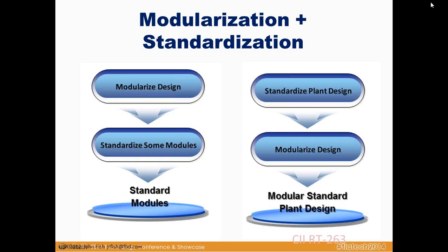They are engineered, they are sized precisely, they are incrementally different. You have to tag every one of them. They have to be custom manufactured, custom tagged, custom ordered, custom received, custom issued. By the time you take what I call the $20 average anchor bolt, if you just built an anchor bolt that was standard, in the neighborhood of 15, 20 bucks, by the time you tack on all the management from individual tagging, that bolt is probably worth several hundred dollars, approaching the $400 mark. So you've taken a $20 item and you've made it worth $400.